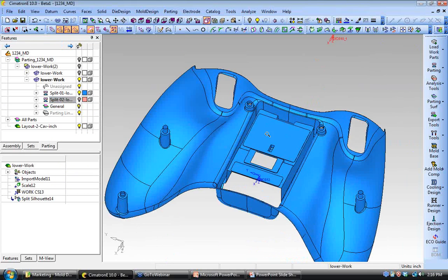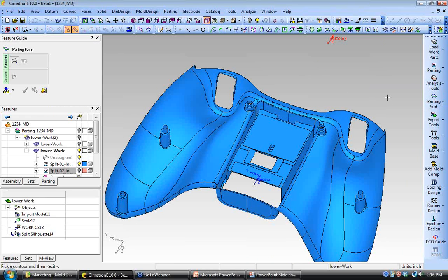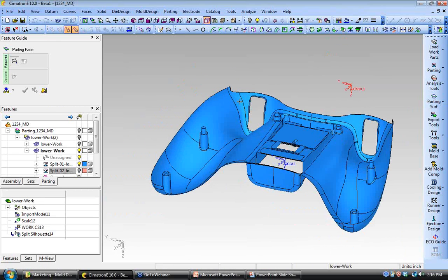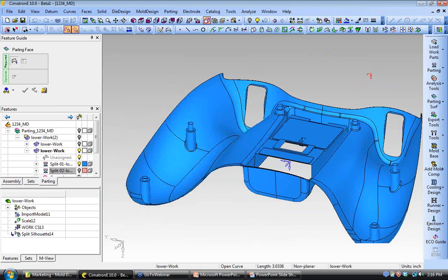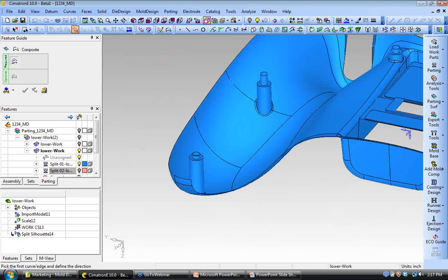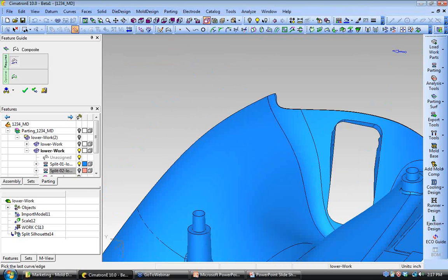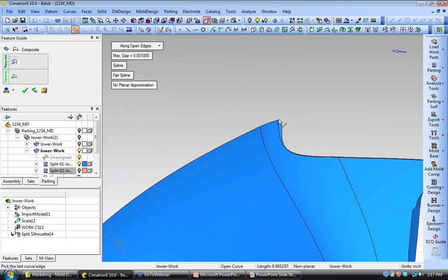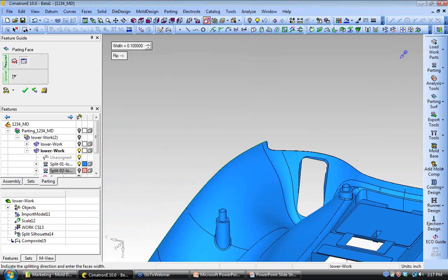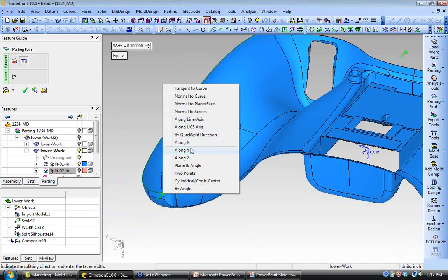So let's look at some parting surface creation options. And the first one we're going to use is called external. It's really ideal for parting lines because it spreads out from the part edges, but it stays as flat as possible to the draw direction. So in the beginning here, I'm going to change some edges. And then I need to fix the vector direction. The arrow indicates draw.